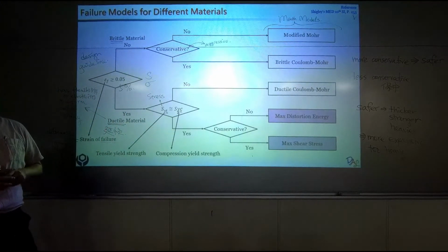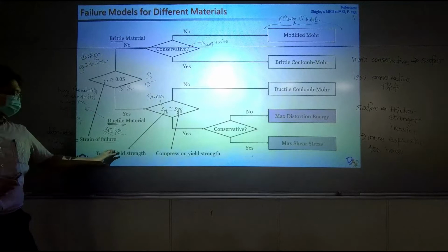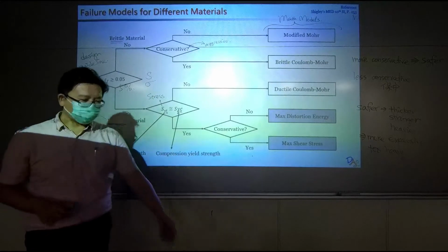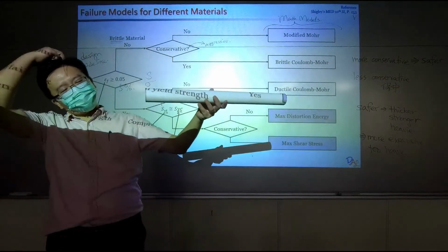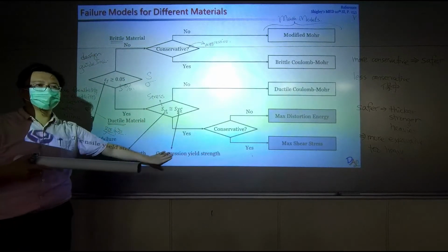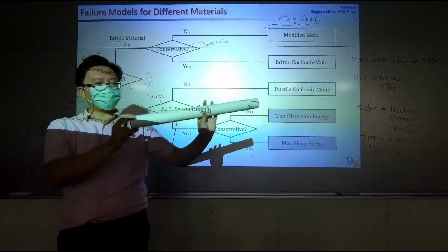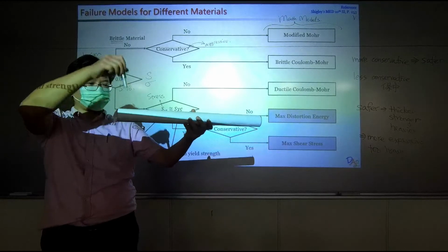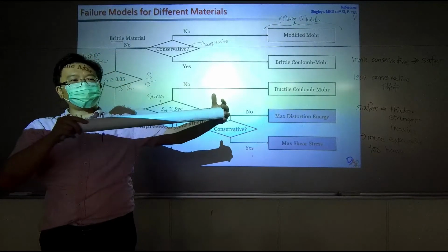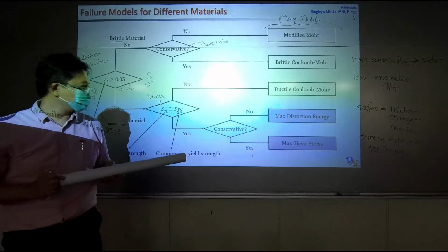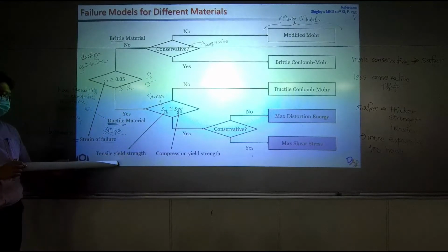So we don't like to study materials which have different yielding strength in tensile and compression. Like what I showed you earlier, if this is a material that has different values for both, then when this cross is on the top and I have force like this, it's under tensile, so how this material can handle this tensile stress is based on its tensile yielding strength.